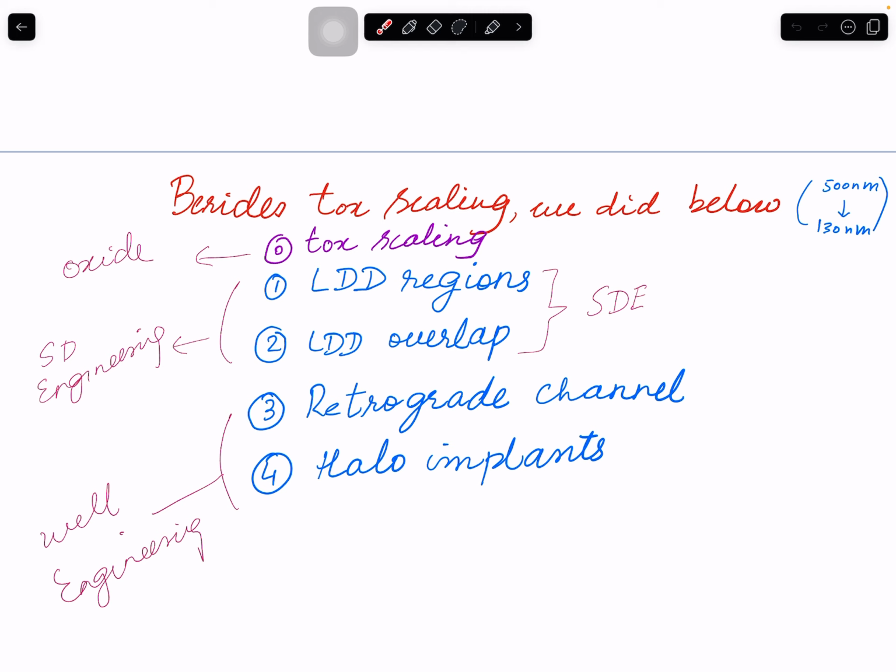Every 2 years, transistor got smaller, and a lot of things went into that. So I think if you understand some of the things, every time a process technology gets smaller, it has impact on delay, it has impact on power, it has impact on density, it has impact on design rule constraints, it has impact on routability, placement, so many things. So understanding some of the things really helps you. It makes you a better designer.